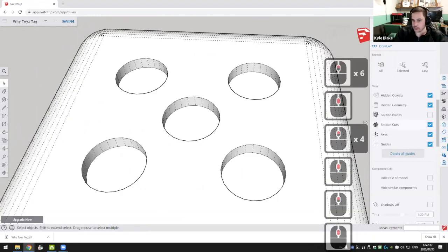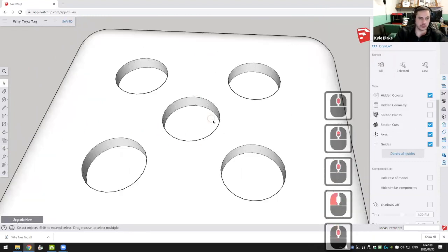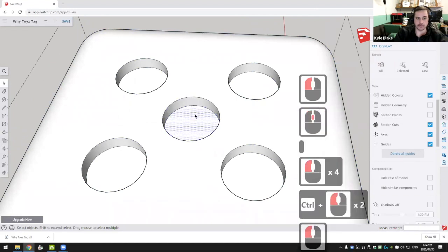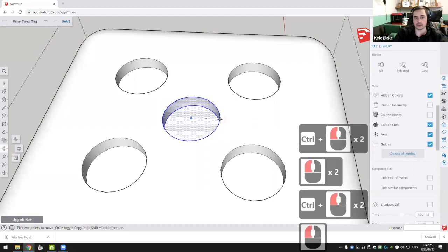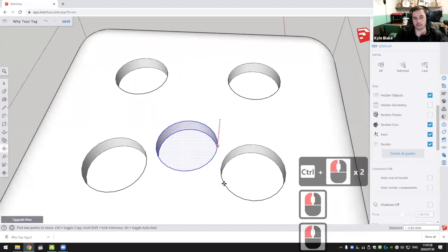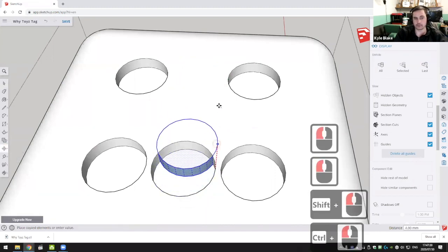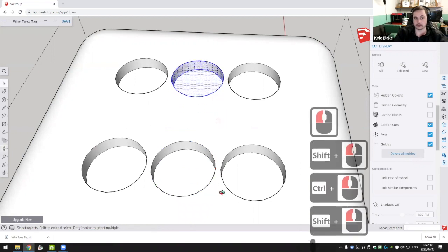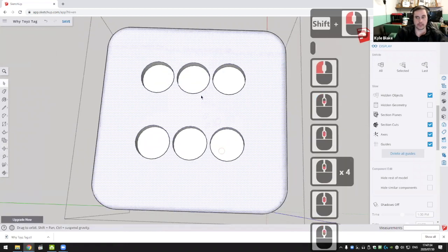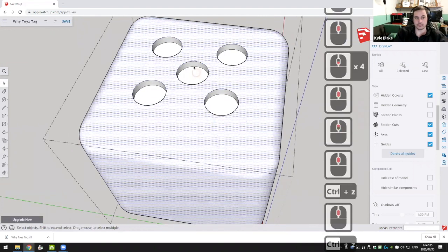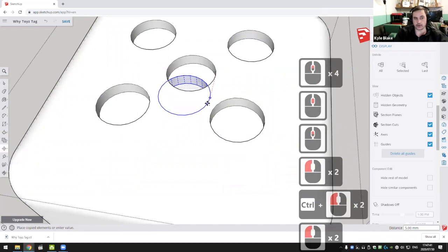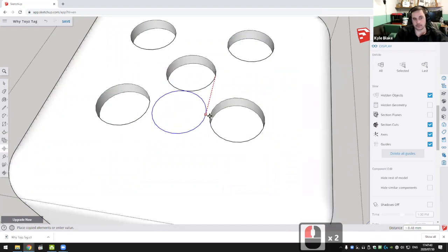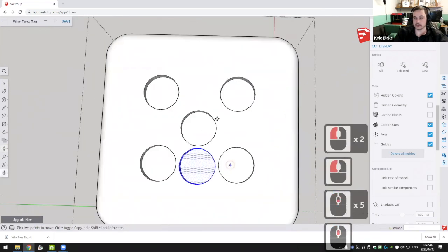You can also move these planes. I'm just going to turn hidden geometry back off. If you double click to select the bottom face and double click to select the face on the inside, you can move these around as well. And you can copy these too. That's exactly the same process. So double click, move, press Control to create a copy, click to place.